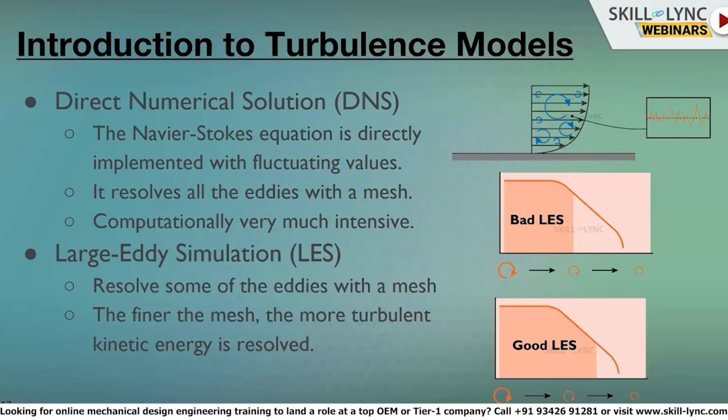And another one is large eddy simulation, which is a kind of industrial plus academic approach, but still it requires a lot of computational power. In LES simulations, we resolve some of the eddies with the mesh. You can see two pictures here. One is labeled bad LES, and one is labeled good LES. So what is the difference?